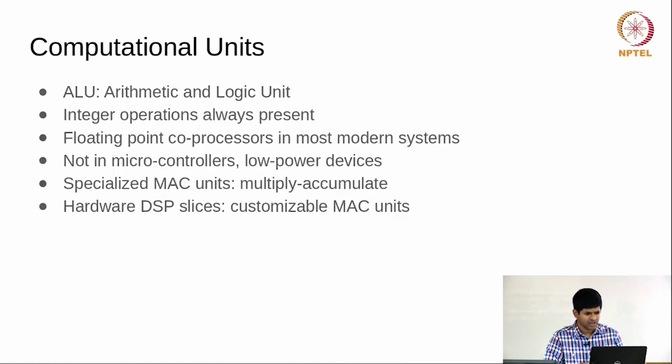Okay. So computational units, typically we are talking about some kind of an arithmetic and logic unit. Integer operations we assume are always present no matter what kind of hardware architecture we are looking at. Floating point coprocessors are very common in modern systems, but as we will see, there could be systems where you don't have floating point natively. Typically microcontrollers and low powered devices do not have floating point.